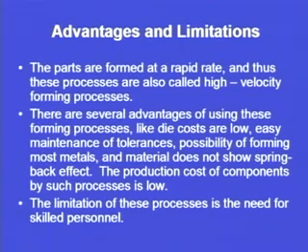and the material does not show spring back effect. So, specifically when we were discussing the bending operation, we have seen that there is a chance of spring back. So, if there is a straight sheet and we want to bend it like this at a particular angle, there are chances that after we release the force that we have applied, it will spring back to a different angle. So, that kind of effects are not possible with these type of high energy rate forming